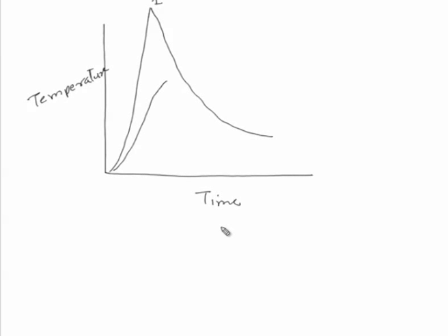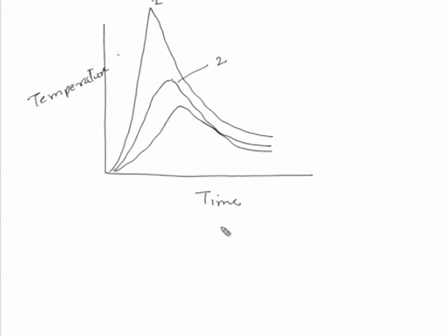Thereafter, if we make the weld thermal cycle corresponding to point 2, then it will experience a somewhat lower peak temperature and lower cooling rates. This is corresponding to point 2. If we take up the weld thermal cycle corresponding to point 3, then it will further have a lower heating rate as well as cooling rate. So, in the weld region, the temperature is found greater than the melting point to facilitate the melting of the faying surfaces.